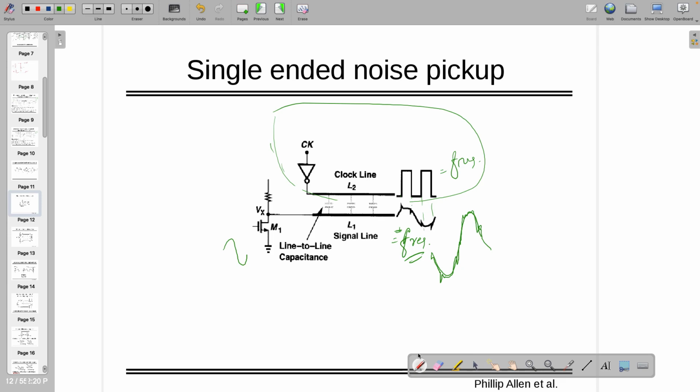One more common source amplifier, whose input is differential. That is what you are saying. Then the output will look like this, but at the same frequency and the same phase. If you subtract both of them, you're going to have double of that, and the output signal is clean. There is no single frequency which was at the addition and acting as common mode, right? So this is what you can do.